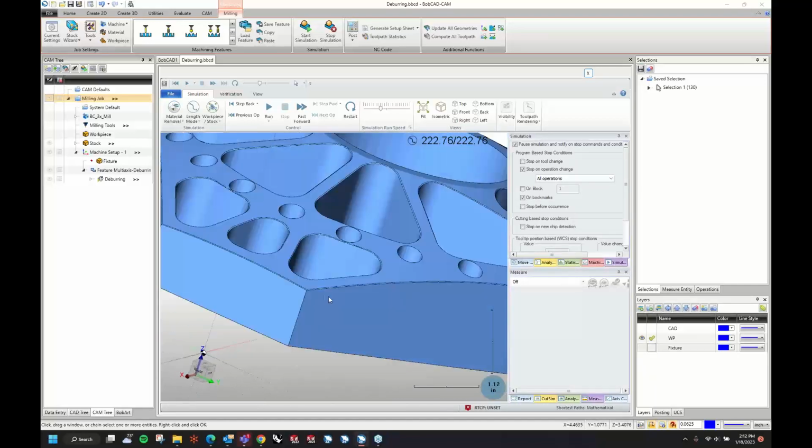This is really the only way you can get that chamfer mill to run this. Now, we have run into some situations where using the chamfer mill, it would not apply geometry. Like I said earlier, it's because of the way that the geometry is shaped. It might not have a contact point. So keep that in mind. If you're using a chamfer mill and it's failing to find a contact point, you're probably not going to get tool paths.